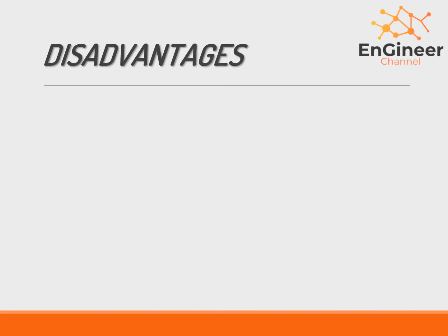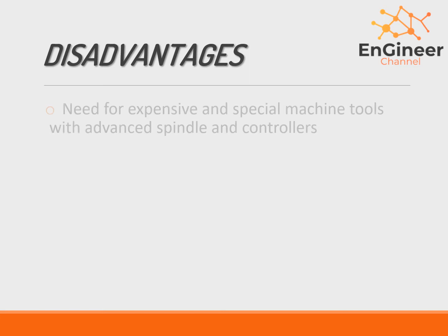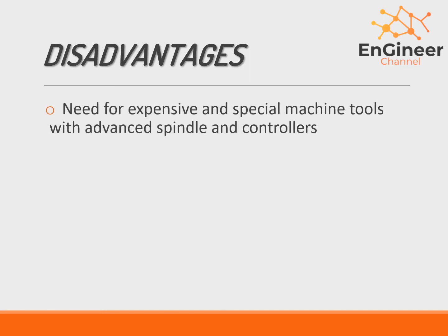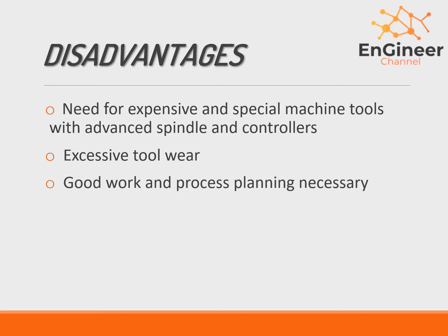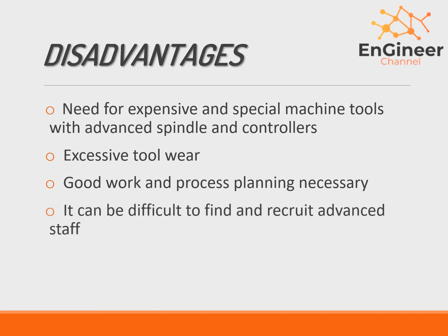Now, seeing the disadvantages of high-speed machining. The need for expensive and special machine tools with advanced spindle and controls. We have excessive tool wear. Good work and process planning are necessary, and it can be difficult to find and require advanced staff.